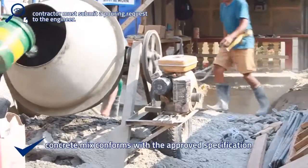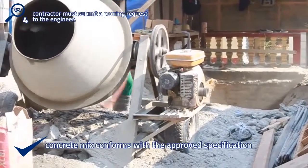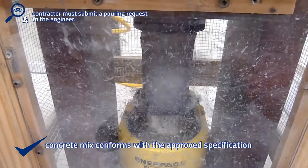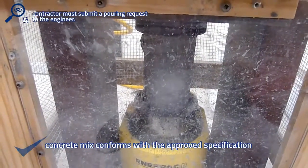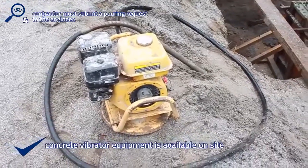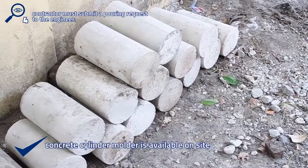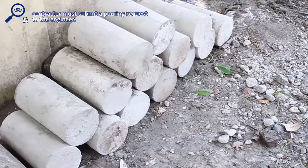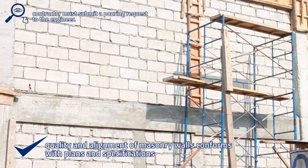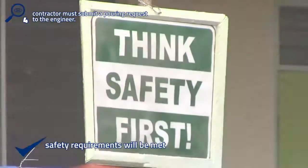The engineer should visit the site and check that the ready-mix concrete conforms with the approved specifications. The required minimum compressive strength must be confirmed as indicated in the general notes of the structural plans. That the concrete vibrator equipment is available on site. That the concrete cylinder mold is available on site. That the quality and alignment of masonry walls conform with plans and specifications. That the safety requirements will be met.